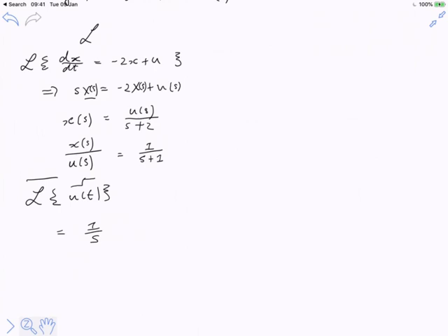I want to say the Laplace transform gave us all these wonderful benefits, right? It got rid of the differential equations. It completely got rid of time. It allowed me to do only algebra and solve a whole lot of different questions about the dynamics of systems. Not only the basic forward simulation problem, but also qualitative calls like, oh, if I calculate the roots of the denominator, I'll be able to determine the stability of the system without simulating, without even trying to invert the Laplace transform, right? So I'm hoping that all of those benefits can be obtained for discrete systems.